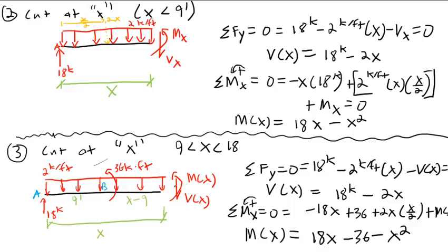And then if we go and get a negative number, then we actually have negative shear, and that's it. So there really is no right or wrong. Just draw it assuming positive shear, and if you get a negative number, you have negative shear. Okay. Can I move on? Okay.